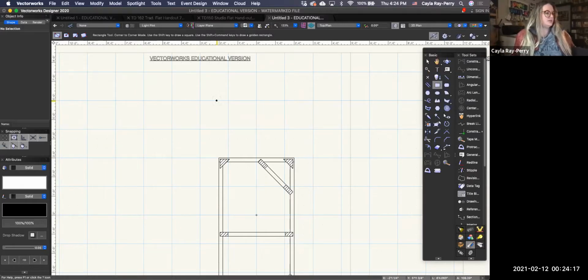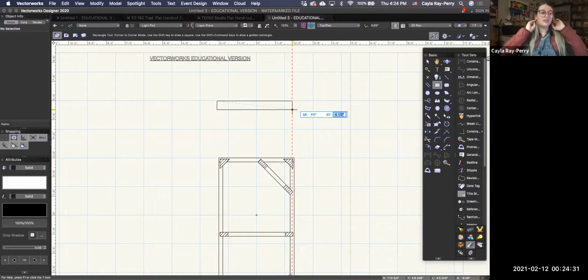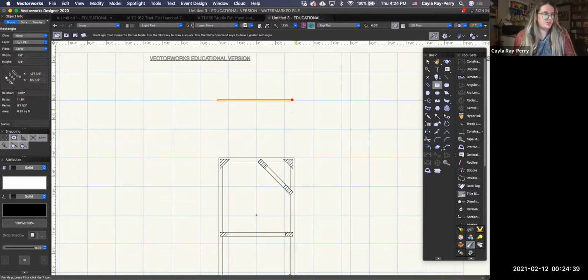And so I'm going to do a rectangle that is 4 feet long. I'm going to hit my tab. And we're going to have 4 feet. And the width of that rectangle is only 3/4 of an inch. So 0.75 inches, enter. And I'm going to hit enter one more time to select it. And that is what our flat looks like from the top, right? It's also known as 2-dimensional scenery for this reason. It's just a fake wall that's almost 2-dimensional, very little dimension to it.